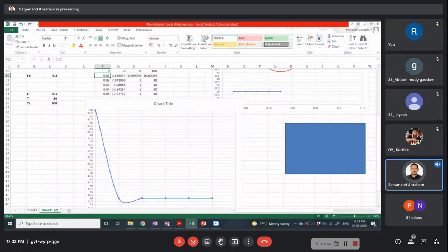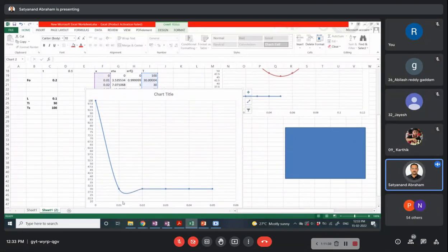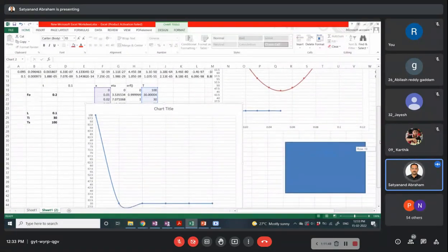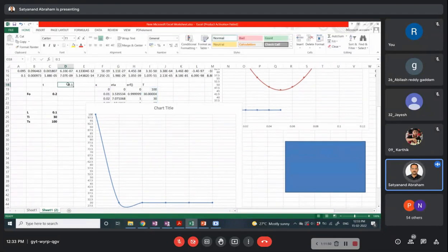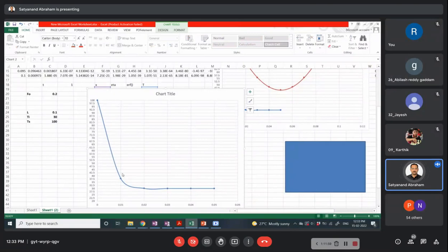You can see that for time 0.02, 0.01, 0.1, everywhere inside is unaware of the change in the boundary condition, right? Therefore, we can call this a semi-infinite solid. Suppose I am increasing to, say, 1 second, we saw that here at 0.1, at 0.01, that means at 1 centimeter, the temperature is increasing.